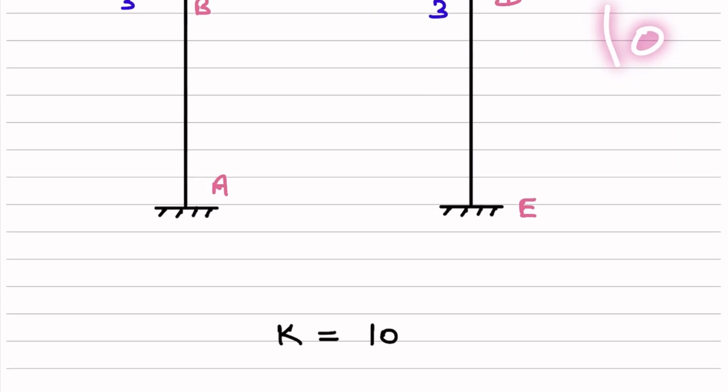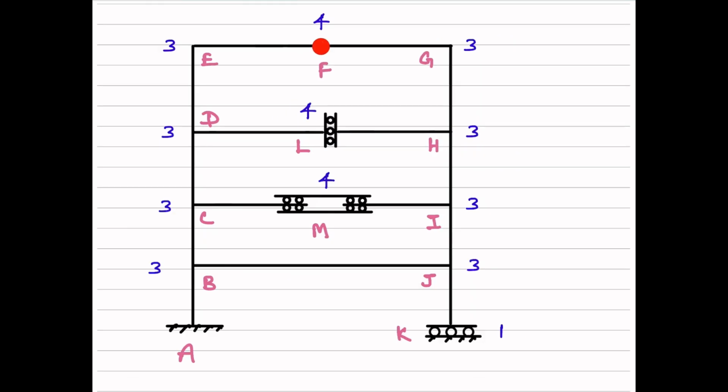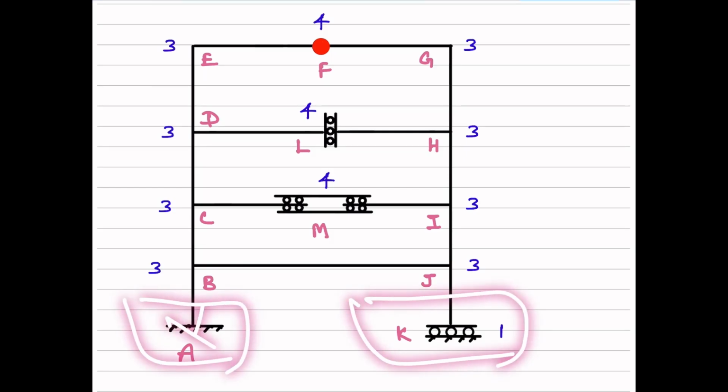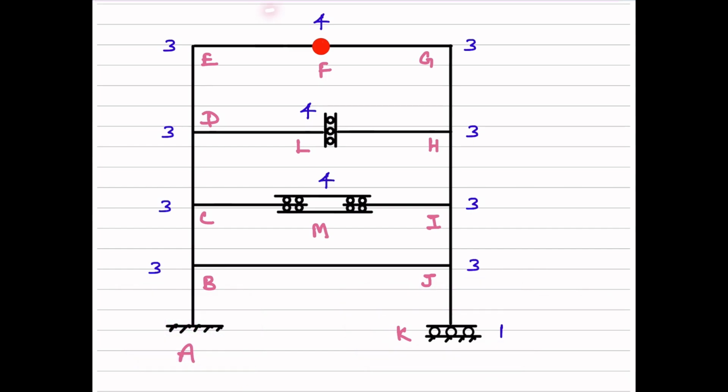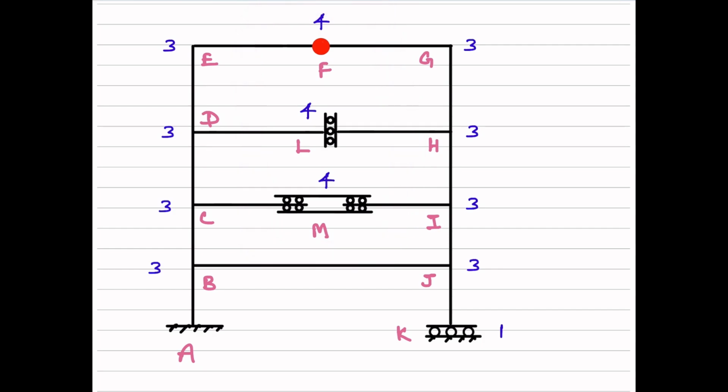And we have the last problem here, which contains all three releases. So we need not bother about these rigid joints much because all of them permit 3 degrees of freedom. So 3 marked everywhere. And this is a fixed support, no degree of freedom. And this is a guide roller support, which permits only this translation and so on. We just need to have a look at these releases here. This is a moment release.